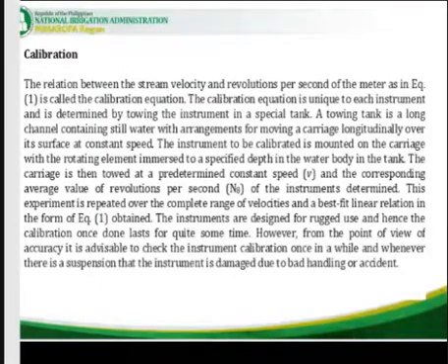The instruments are designed for rugged use and hence the calibration once done lasts for quite some time. However, from the point of view of accuracy, it is advisable to check the instrument calibration once in a while and whenever there is a suspicion that the instrument is damaged due to bad handling or accident.